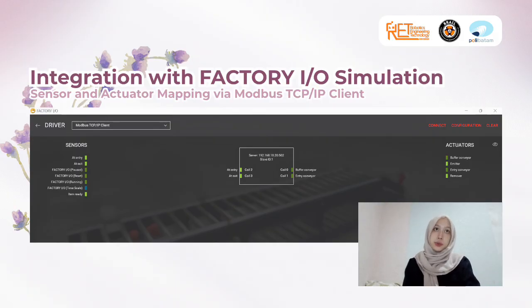And then we have add entry as the sensor that gets mapped to coil 2, and then add exit as the sensor that maps to coil 3. Also the buffer conveyor as the actuator that maps to coil 1, and the entry conveyor as the actuator that maps to coil 0. So this mapping is basically the bridge. It connects the physical objects in the Factory I/O scene directly to the variables that have been declared earlier in the PLC program using the exact offsets I just explained.